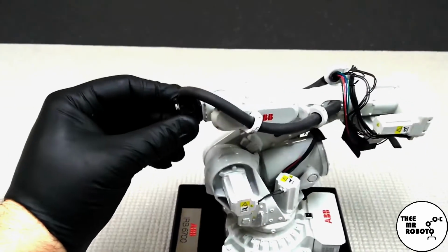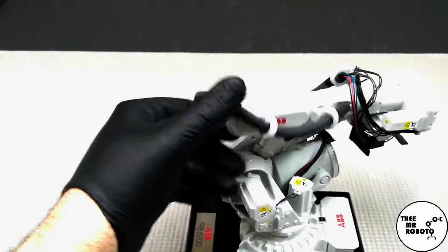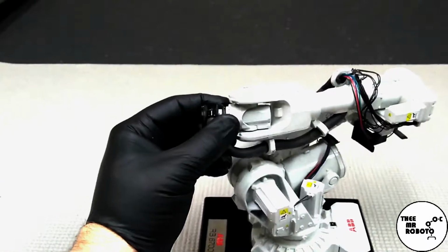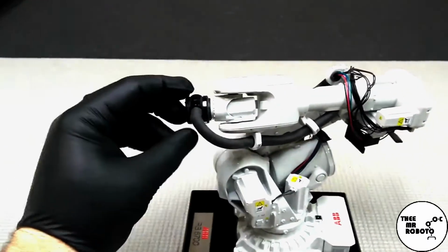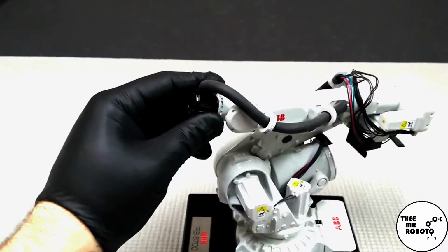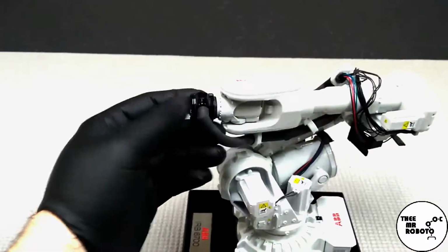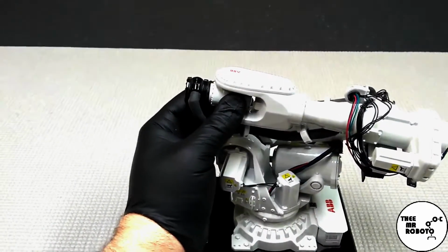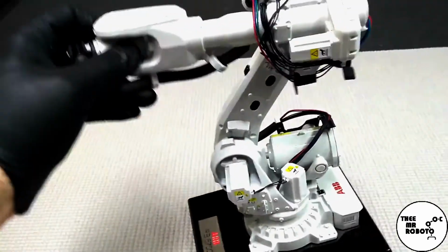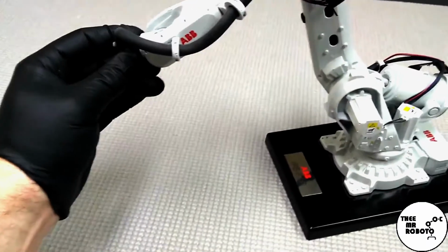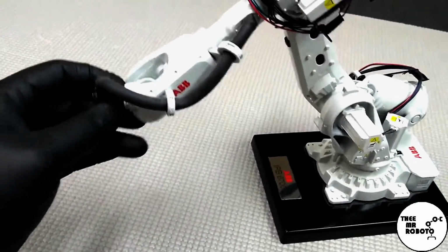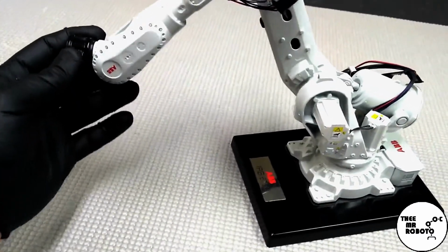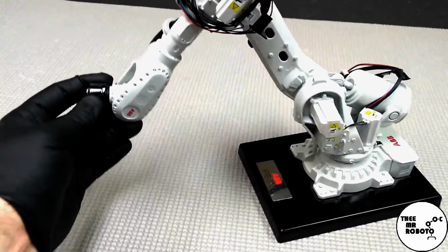So that would mean that the robot would try and rotate all of its joints so that you could create a positive Y motion with the flange, all right? This is kind of hard to do with one of these robots, but try and just get the understanding here. It's a Y, it's coming towards me. Let me stretch this guy out a little bit. It might help a little bit. A Y motion towards me is like this, where the wrist rotates and it allows the programmer to make a perfectly straight Y direction motion, okay?